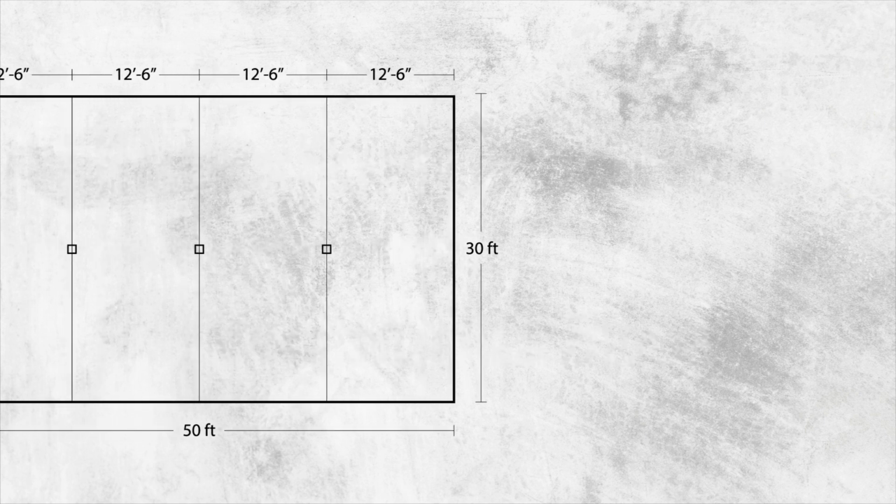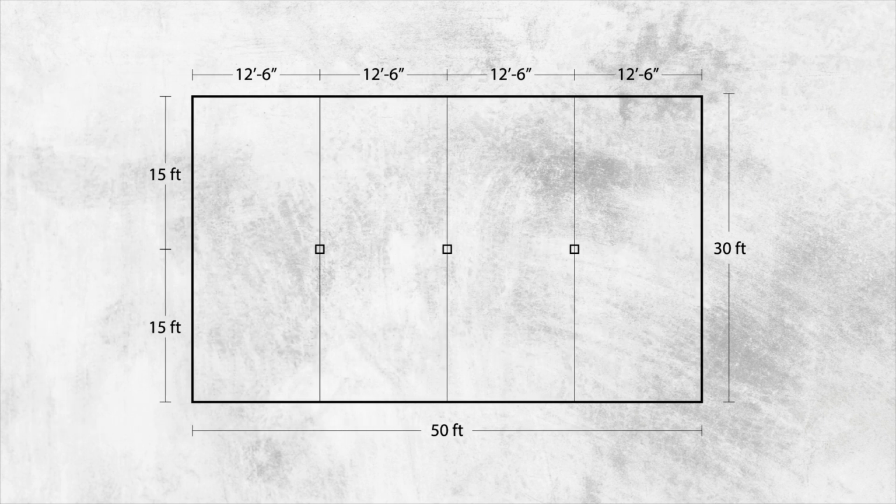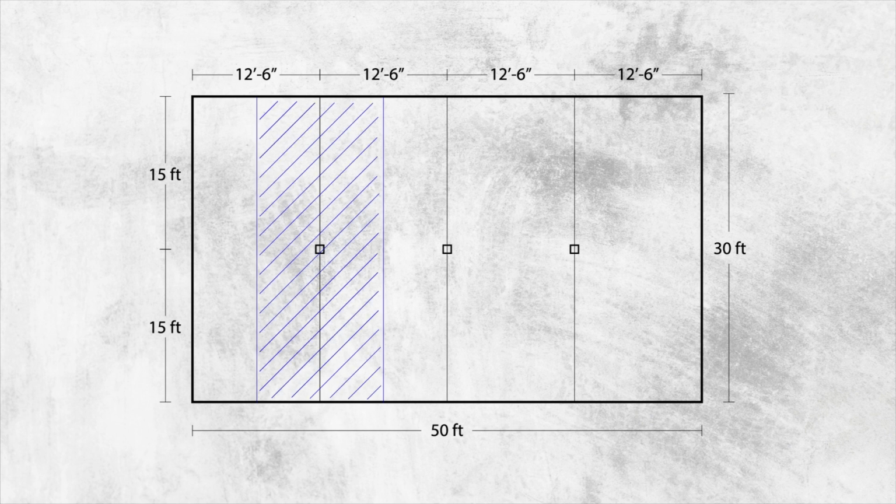If the slab is placed on top of the beam, then load is transferred to the beam through a one-way or two-way system, also known as a one-way or two-way slab. For our case, the system is one-way. This shaded region is transferring load to a specified beam.